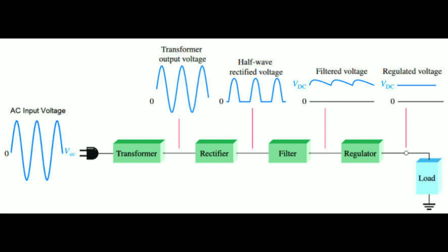To better understand, let's define what a power supply is. A power supply is a device that delivers electric power to one or several loads. We generate the output power by converting the input signal into an output signal. In designing a power supply, we must know the components that we are going to use. To better project the design, this is a block diagram of a DC power supply. Our block diagram consists of four main sub-blocks, namely the transformer, the rectifier circuit, the filter, and the regulator.